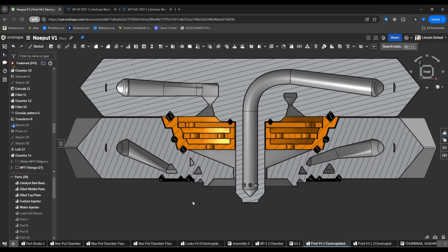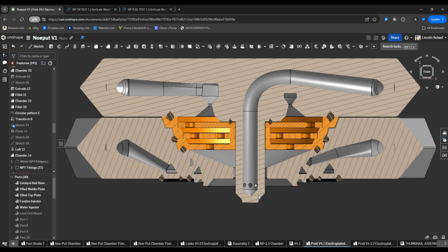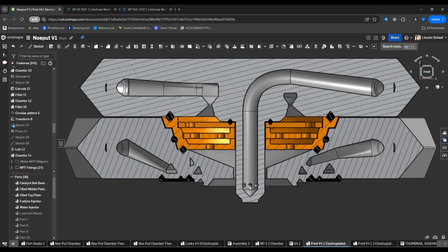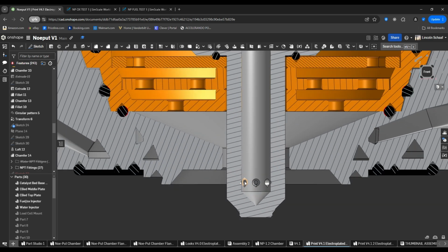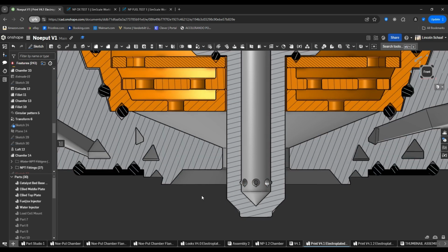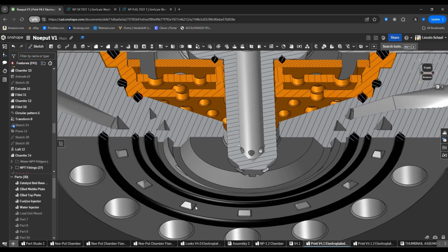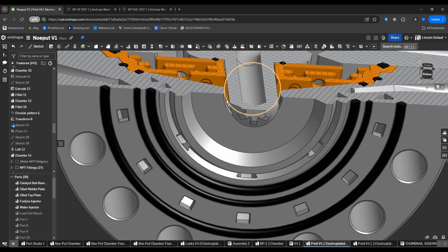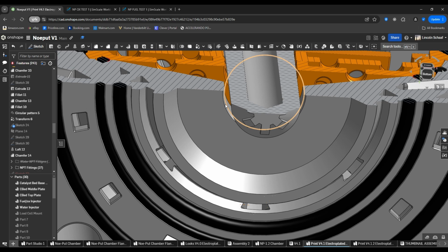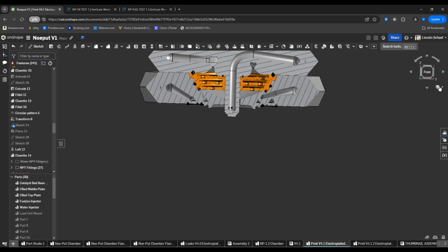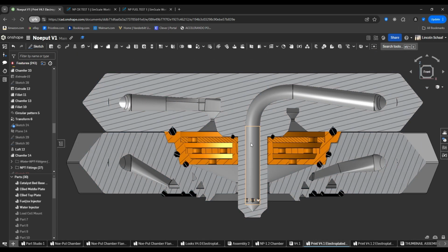Using this pressure and the mass flow rate, we calculated the total area of the exit for each propellant. In the case of the ethylene, we divided that by 7 because there's 7 holes in this pintle. For the nitrous oxide, we had to find the area between 2 circles, a ring, and use that to get the outer radius.